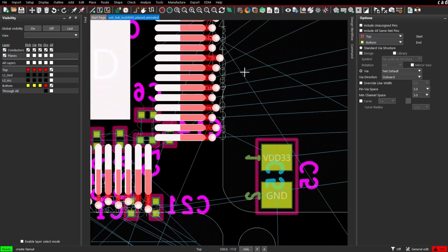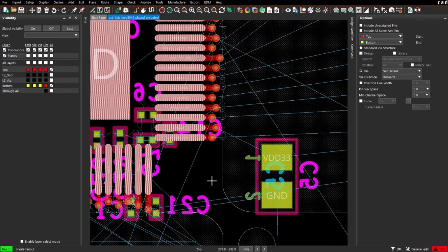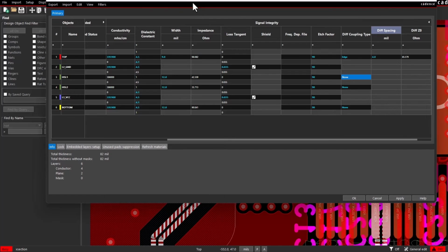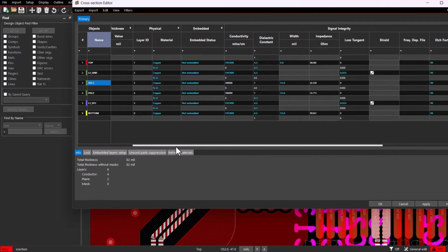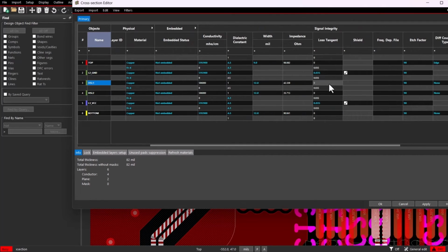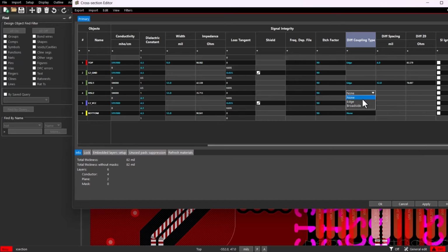Keeping those rules in mind, I would route my critical traces first, well, after my fanouts, then any high-speed signal traces. Depending on the PCB, you may want to route them internally on a 6-layer PCB to shield them from EMI, and also to trap or guide the electromagnetic waves coming off those high-speed signals from traces on the top.